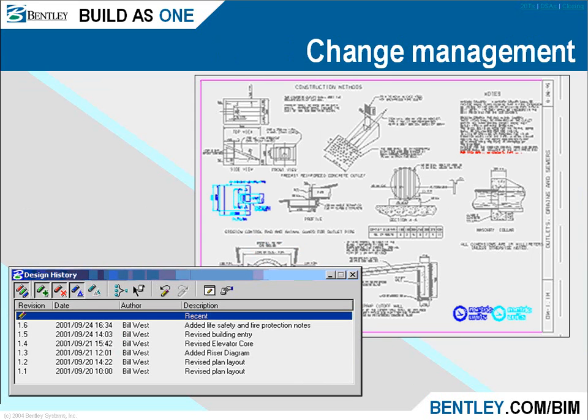And for change management, this is through design history. Think of design history as unlimited undo. Basically, I can keep versions of the drawing, get out of the file, and come back 3 weeks later and return the drawing back to its original state or any version or revision thereof. I can also do a design compare showing the differences between the different revisions. Green would be things that were added or new. Blue is modified. Red is deleted.